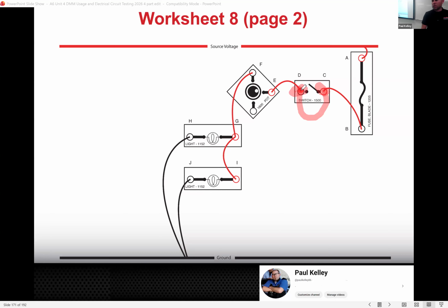What am I doing with that fuse jumper? Making a complete circuit, if it's open and the switch doesn't work. The word I like is a bypass. If I bypass the switch and it fixes it, it was because the switch wasn't working. Right? So fuse jumper leads are legit.